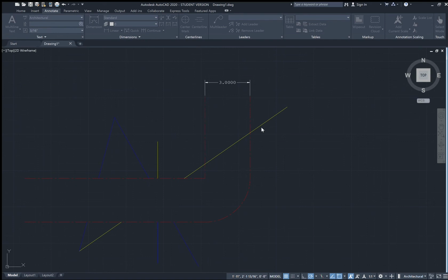Continue. And here there are lots of different settings you can change. First thing, we're in the primary units tab. The unit format is decimal. If we change that to architectural, you'll see in the sample it now displays inches, which is what we want. We can also mess around with everything. The text style we set to architectural like before, in Courier New font. We can change the text height as well. We can make the text height 3/4 of an inch if we wanted to.